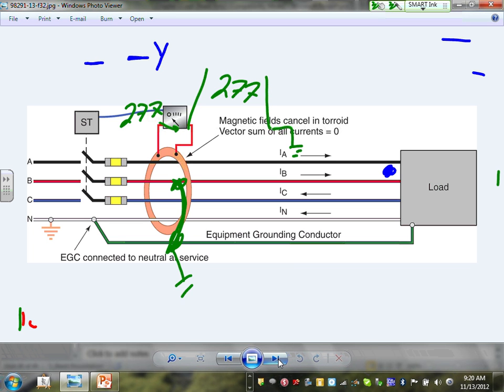You know, 6 feet will be extending if you have a tank sitting there and you have a transformer right next to it. 6 feet, 10 feet, probably I will bond it, just in case something gets electrocuted. A tank can have a pump next to it that could energize that tank. You bond it. So judgment, 6 to 10 feet, I would say.